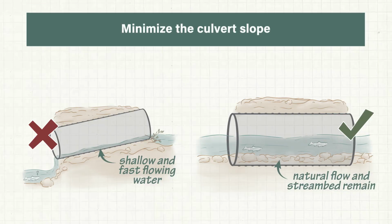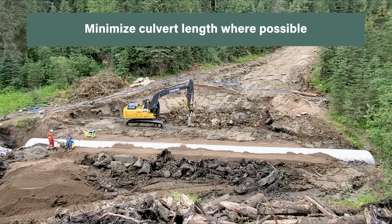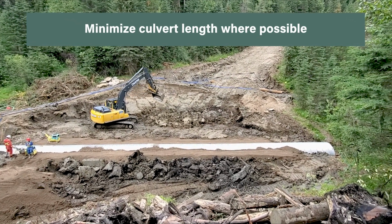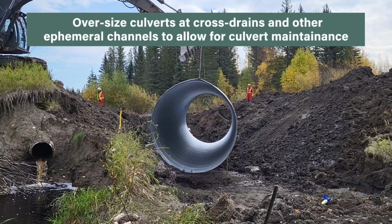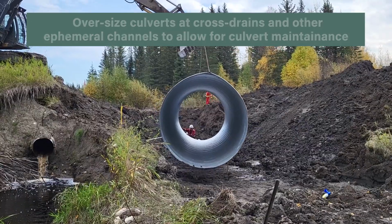structure. Minimize the culvert slope to avoid high water velocities. Minimize culvert length to avoid adversely high velocity for long distances, which can make fish passage more difficult. Consider oversizing culverts at cross drains and other ephemeral channels to allow for culvert maintenance.